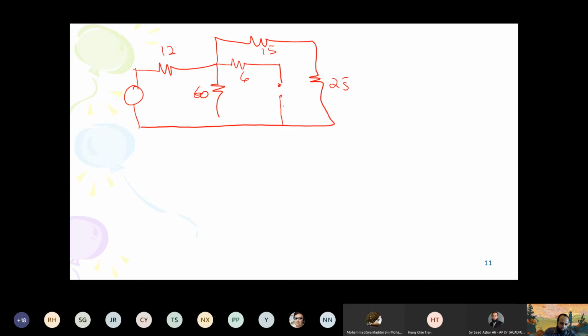All right. So we are looking for this voltage, because this is important, as in the questions the initial conditions might not be given. Just to give you a recall, whenever there is an open circuit, you go back to one end of one branch and go back to the other one, because it is open circuit, there is no current here. So we are looking for this voltage actually. Do you guys agree with this?